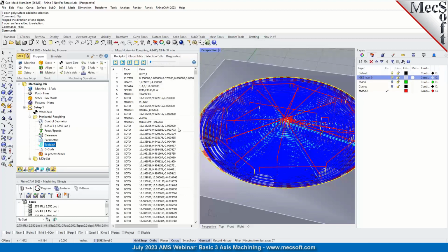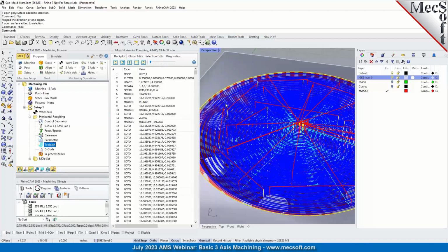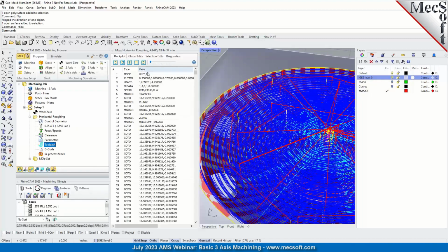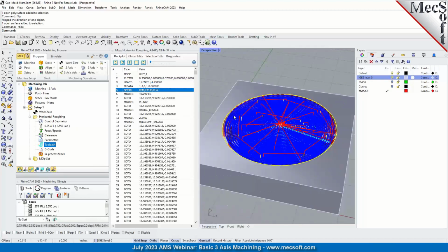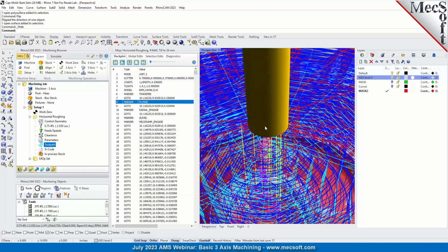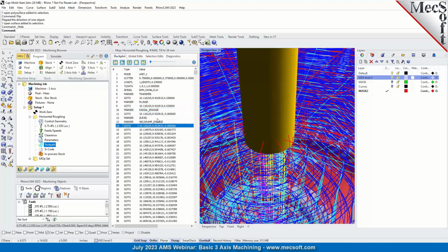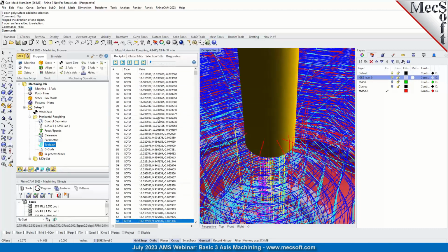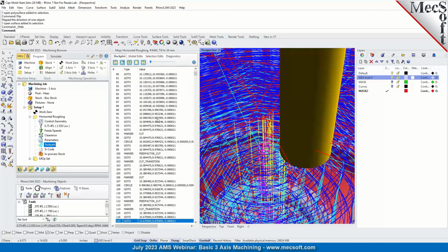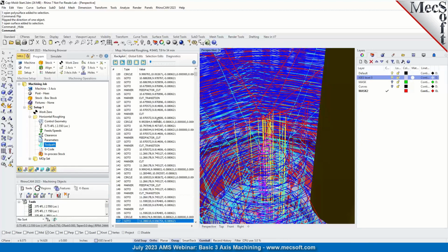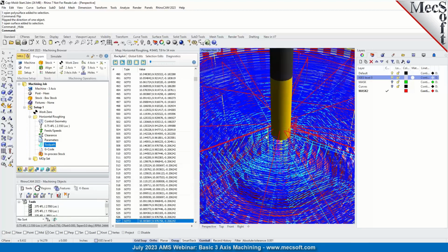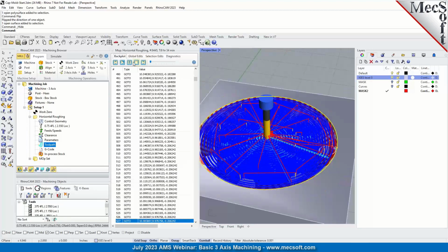If you're in the professional or higher, you have other tabs that you can do some actual editing on the toolpath at this point. But if you just want to see where the tool motions are, just start at the top and use the down arrow, and it'll locate the tool at the start point, and it'll just start going through the actual motions here if you want to do that. If you want to do it fast, you can hit the page down and it'll go really fast. So we don't really need to do any of that.